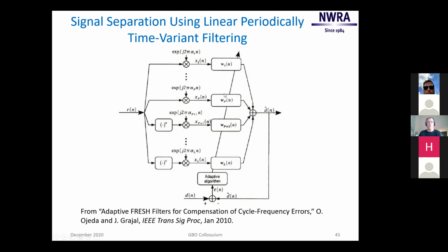And so no surprise, the frequency shifts that you pick for this to work well are cycle frequencies. They're cycle frequencies of the signal that might be in R, as well as the interferers that are in R, and their sums and differences and linear combinations.